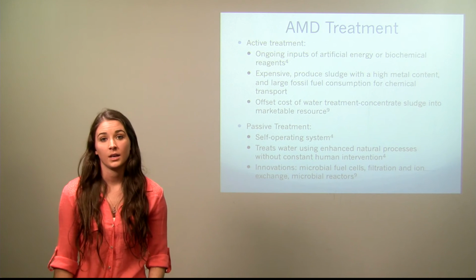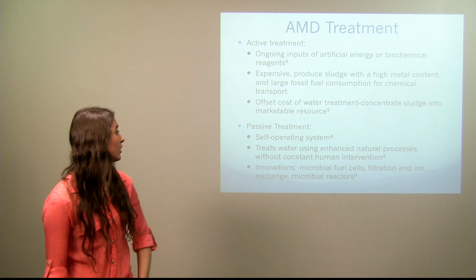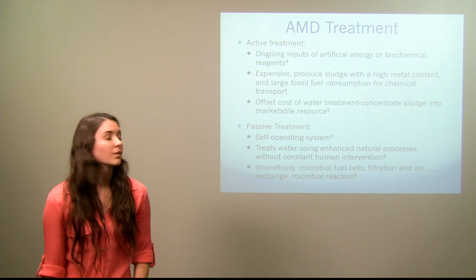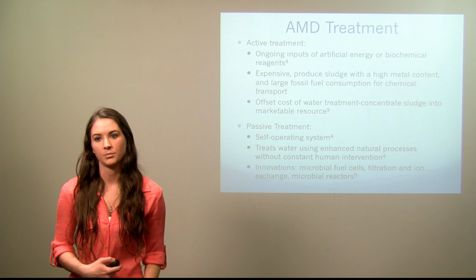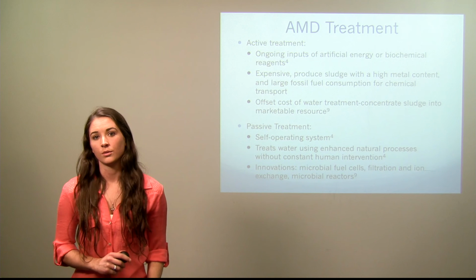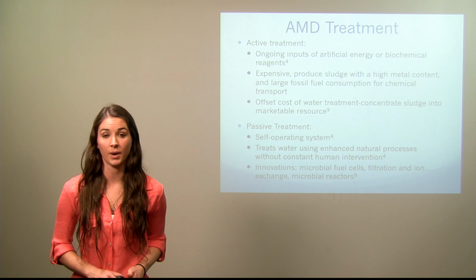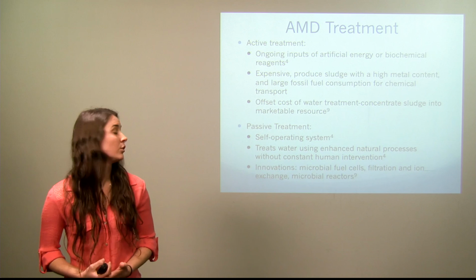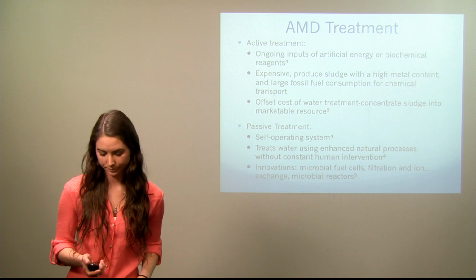Passive treatment is a self-operating system that treats the water using enhanced natural processes without constant human intervention. There has been a particular interest in the passive treatments because of the low operation and maintenance costs, and full systems have been constructed with constructed wetlands and bioreactors. However, new innovations are being looked into, like microbial reactors, microbial fuel cells, and filtration and ion exchange.